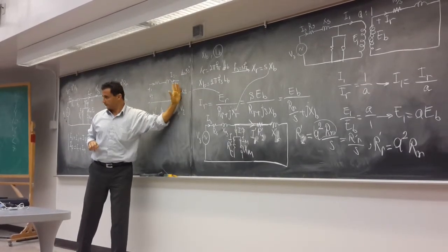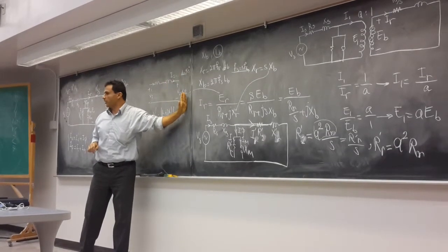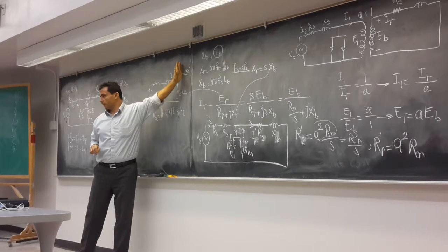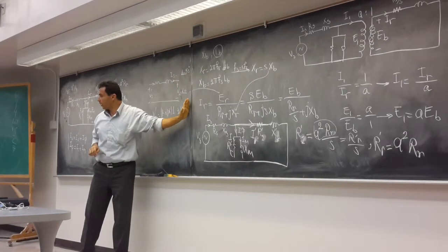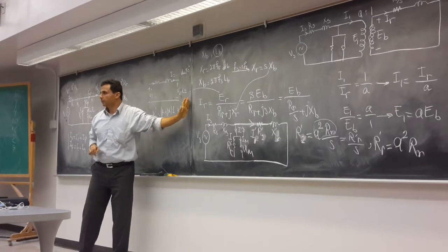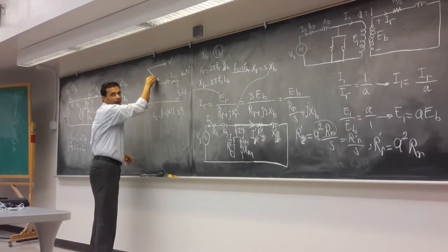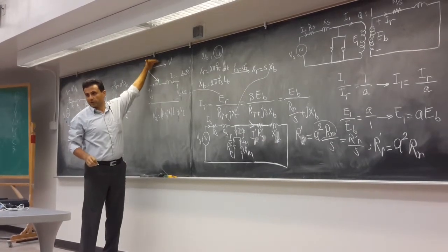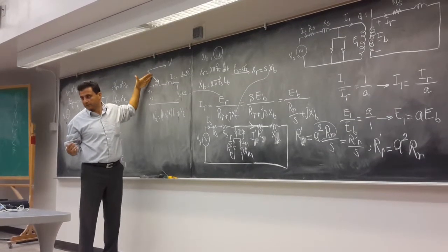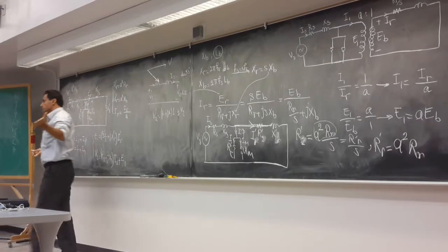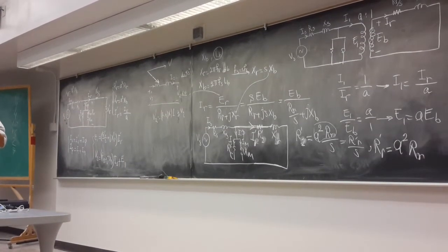This is your reference, right? 0, minus 53. If you put this one at 90 degrees, how much should this one be? 90 minus 53, right? Whatever this one is, minus 53, this is lagging. We talked about this one. This is a voltage. When we say lag, the current is behind. If this one is 0, this is negative. If this one is 90, this is 90 minus this angle. And I'm surprised only 1% in the whole class did this one. It's very surprising, I don't know why.